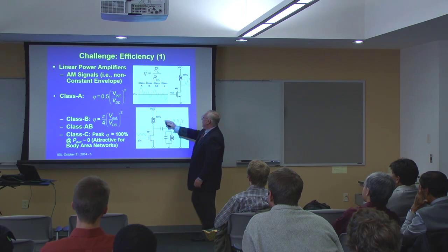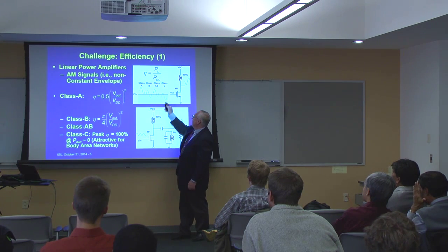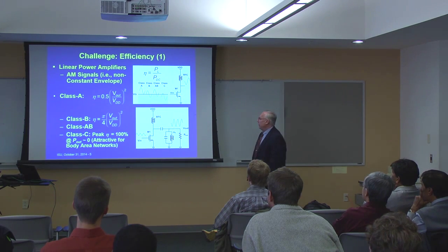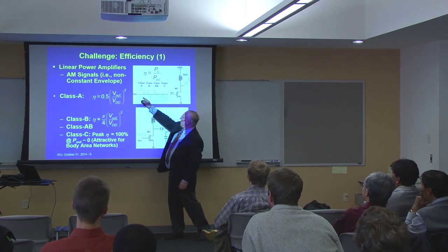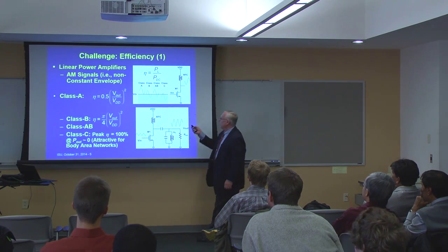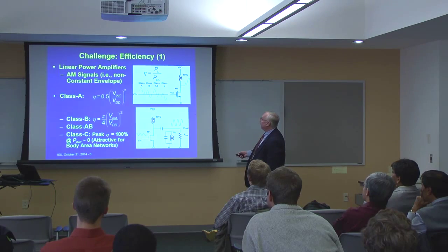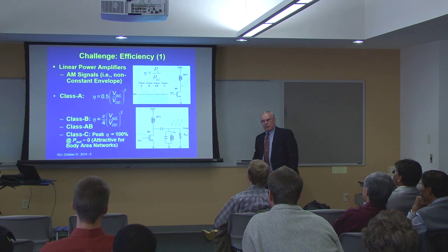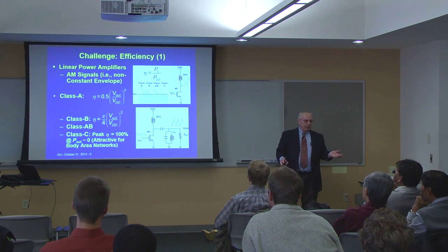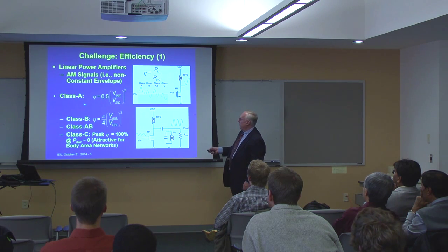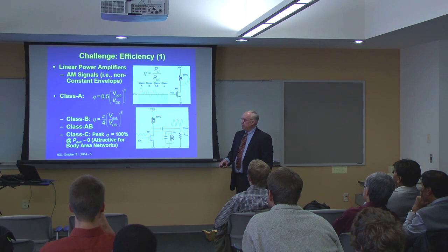So this is a nice little chart that I like to use to show the different definitions for the different classes. So what this says is that if you have the threshold voltage for the MOSFET, I probably should use this. Whoops, not that. See, that's why I don't use that. If the signal is always above the cutoff, in other words, the amplifier stage is on all the time, that's class A, and class A in the RF world has a maximum efficiency of 50%.